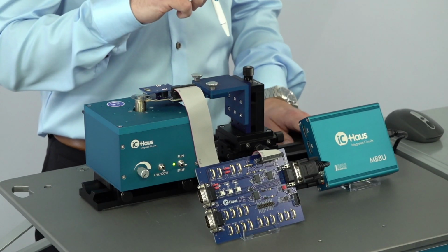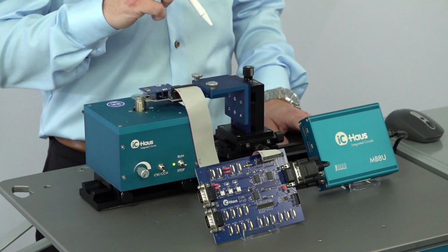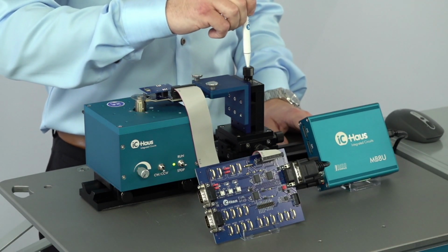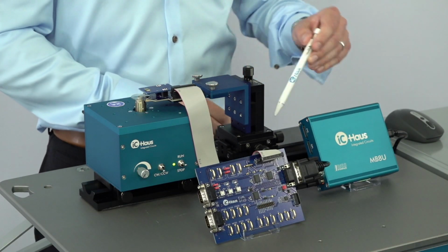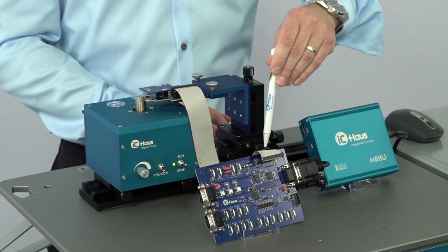Aside from these components, everything is mounted onto an iC-Haus test stand, which, by the way, if this is helpful to you to get started in the lab, please feel free to reach out. We can provide it. It contains a motor with an integrated reference encoder, and extremely helpful are those micro manipulators here. So I can really fine-tune the mechanical alignment in Z-axis via this micro manipulator, in radial axis via this manipulator, and in tangential axis via this manipulator.